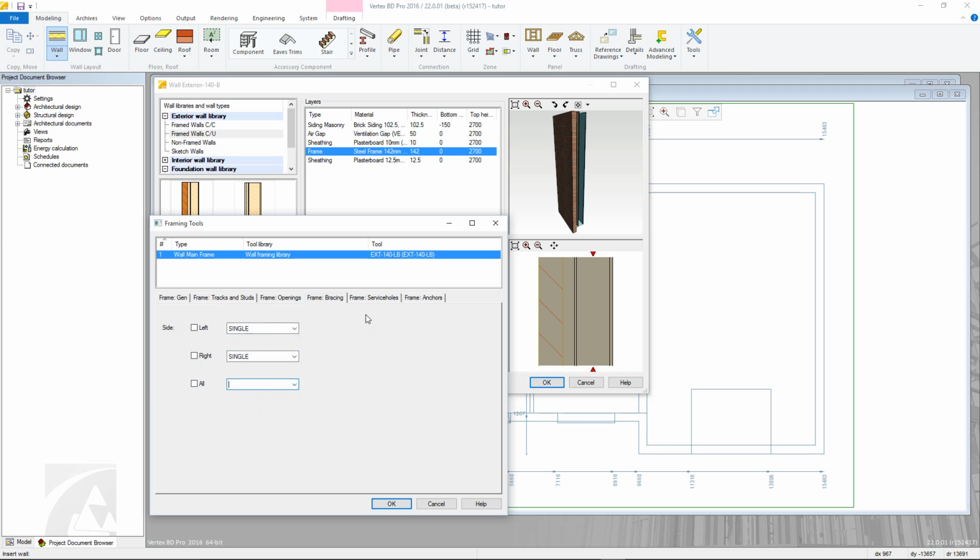In the Frame Service Hole tab, you can customize service holes further from the default setup in system parameters. Default takes the value previously defined in the system parameters. The user can then override this by typing in the required heights. You can also determine the hole type used from the drop-down menu. However, this will depend on the tools available on the roll former.